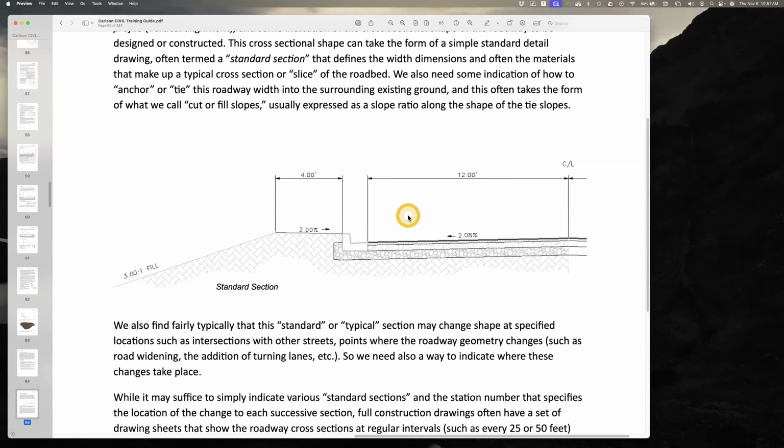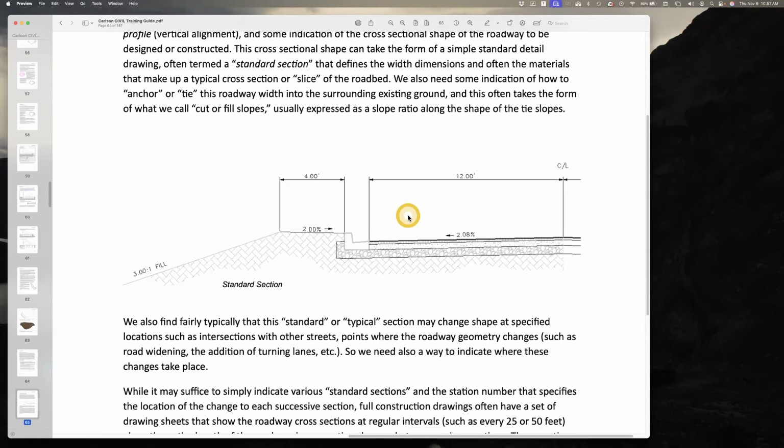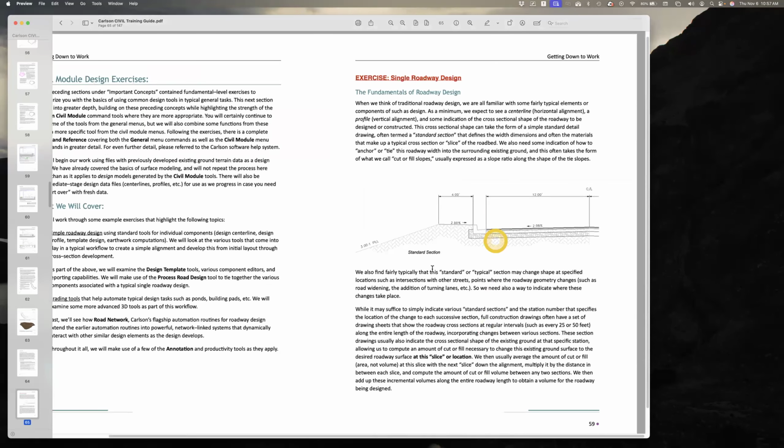And so that is going to be pushed through our site horizontally, whereas a typical site design approach would be to design it from the bottom up. You draw the closed outlines of the edge of the pavement, and you'd say, okay, this is my area, and inside that area I've got so much stone and asphalt or concrete and sand, all the different things that make up that outlined area.